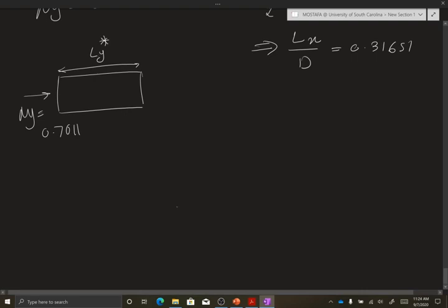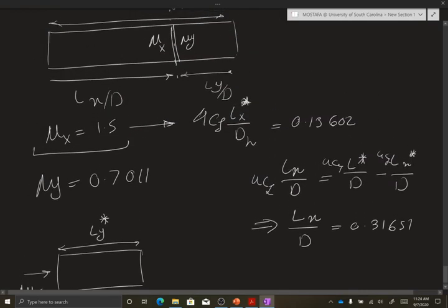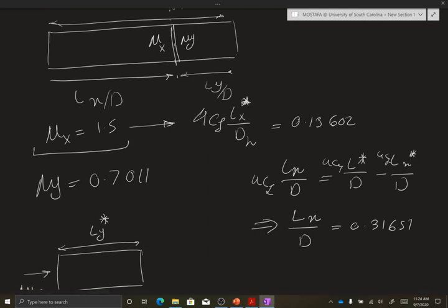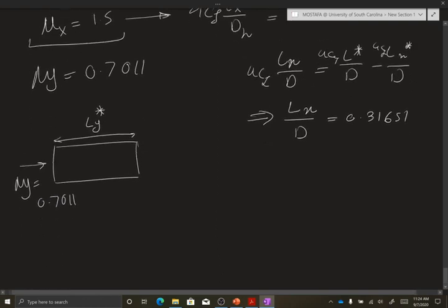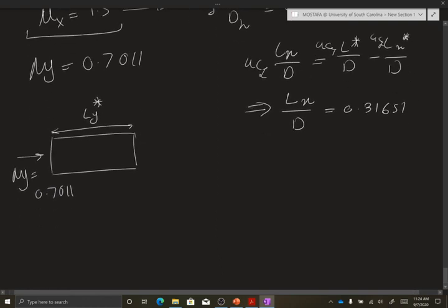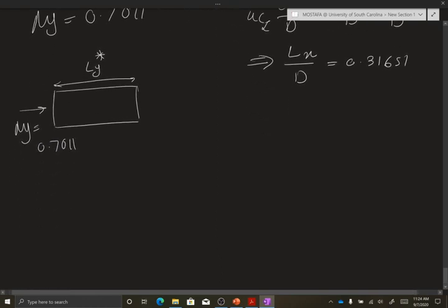That is the idea, because the normal shock happens and the choking happens. Because the choking has happened inside the duct, we have the normal shock for the flow adjustment, so that the exit condition will be the star condition, M star equals 1. That was the idea of choking in general. So we already know that Ly is Ly star.